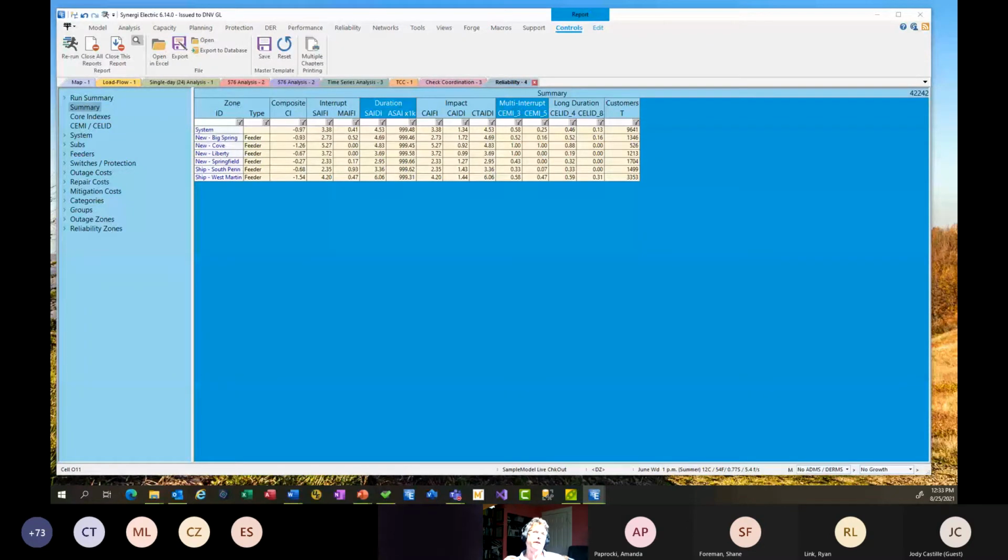So if you think about, let's say we've got a load of 50 kW. This is what I call the nameplate. So you've got 50 kW in the editor, and you have a load profile that's at 50%. Well, the actual load is going to be 25 kW. 50 kW times 50% gives us 25 kW, so when we run load flow, we would see 25 kW.